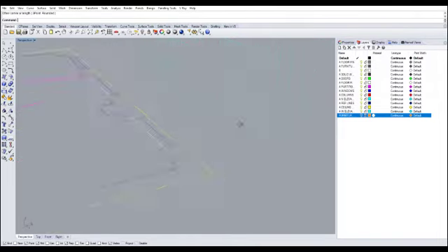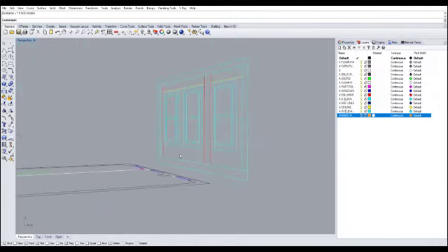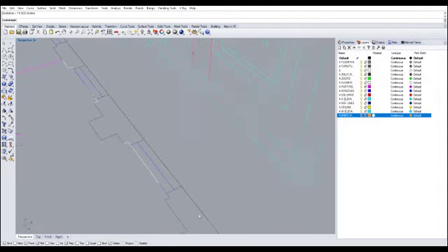So what we're going to do is extrude or make a ground level 3D and tall enough to fit this height. Now we don't know what this height is yet. We can measure it by typing in distance. Because we have our OSnap on, it should snap nicely. So snap here, it tells us it's 11.5. Now we can use that information to extrude our ground level.